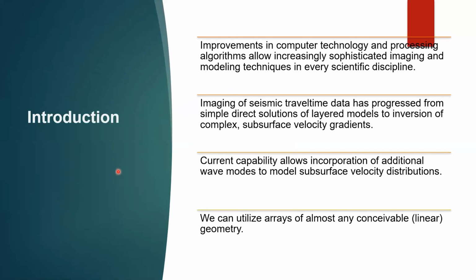So essentially, by using tomographic inversion techniques, we are able to develop two-dimensional models of complex velocity distributions using just first arrival times and array geometries for input. Now, combining these models with observed borehole geology or other geologic information available on the site allows us to assess data gaps and to develop satisfactory geologic interpretations of the velocity structures with a high degree of constraint. So I'll hit on three basic discussions here. One will be an overview of modeling techniques. I'll talk about uniqueness and optimization in modeling. I'll talk about some of the advantages we've achieved using novel seismic arrays for site investigations, and I'll present results from two Northern California examples.